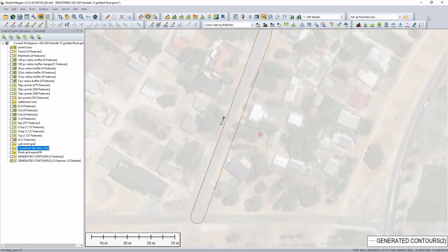So this slope angle here, we're obviously looking at really small slope angles of less than 1 degree, but on a district-wide scale, the same function can be used to extract vectors for breaks of slope, say for gully crests on an entire watershed. So it's a really, really versatile tool.